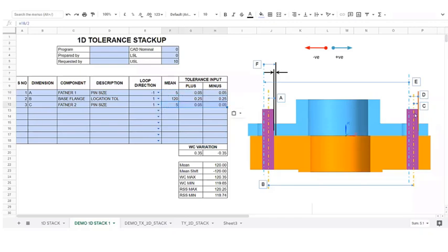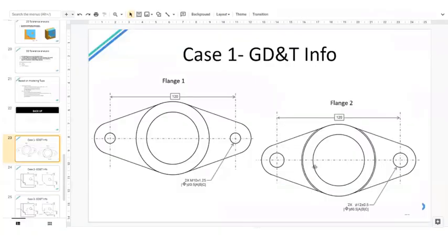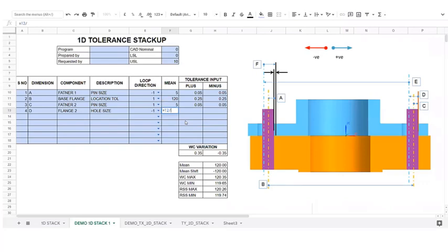Okay. From there, we are again moving to the left end of this surface, which is where the part transfer happens, and then from there we are going to the axis of the hole. So the direction is negative, and the size of the hole is 12 plus or minus 0.5. So we need to take 12 by 2, so plus or minus 0.5. You need to give 0.5. So I think the same we need to apply over here.